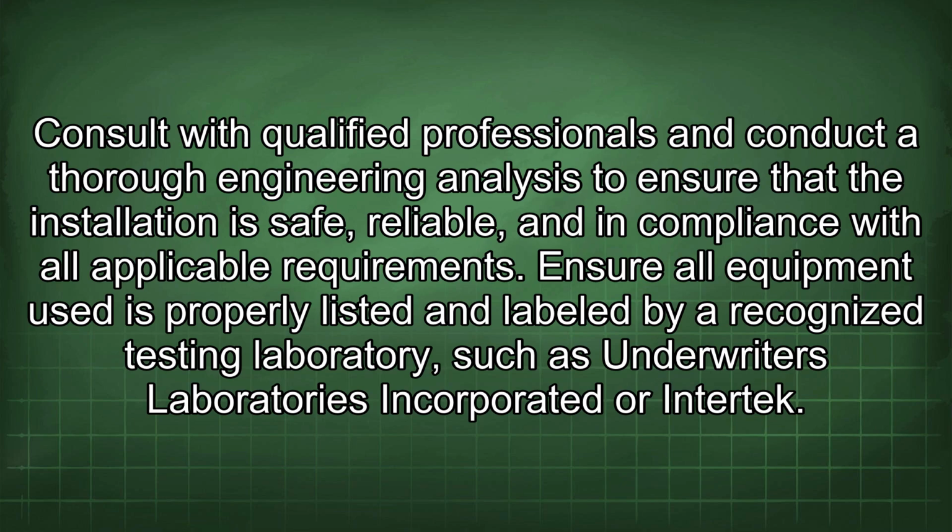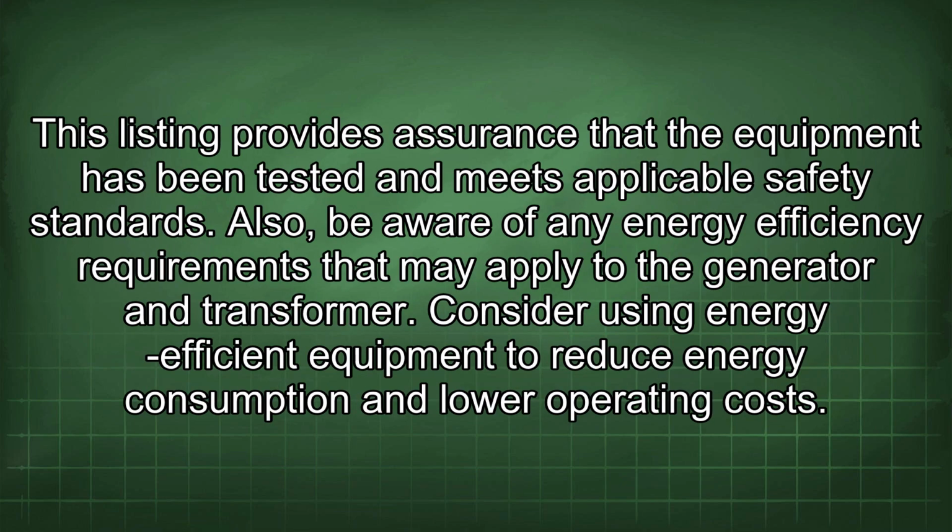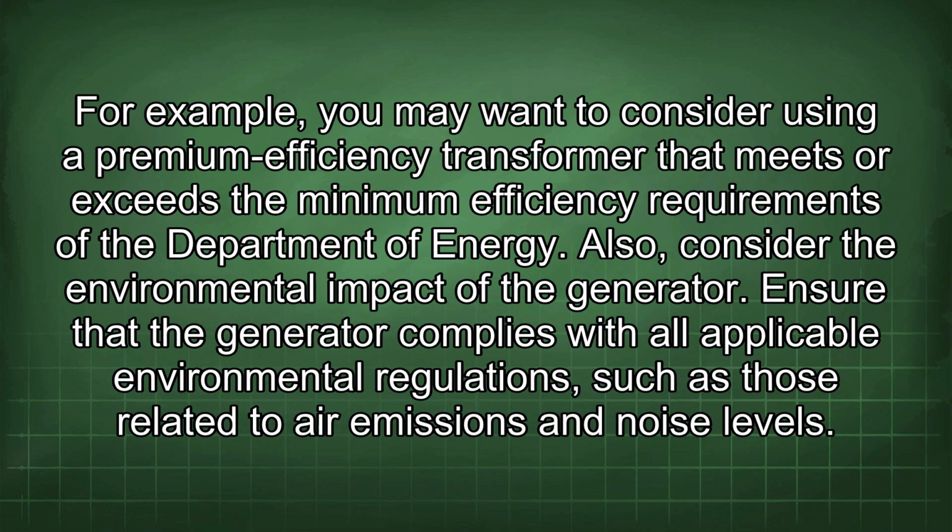Ensure all equipment used is properly listed and labeled by a recognized testing laboratory, such as Underwriters Laboratories Incorporated or Intertek. This listing provides assurance that the equipment has been tested and meets applicable safety standards. Also, be aware of any energy efficiency requirements that may apply to the generator and transformer. Consider using energy-efficient equipment to reduce energy consumption and lower operating costs. For example, you may want to consider using a premium efficiency transformer that meets or exceeds the minimum efficiency requirements of the Department of Energy.